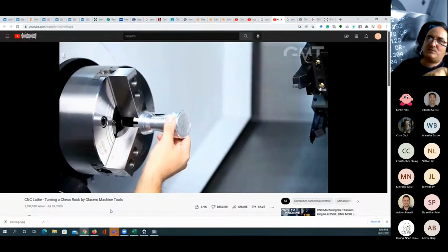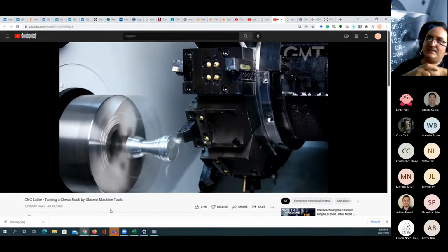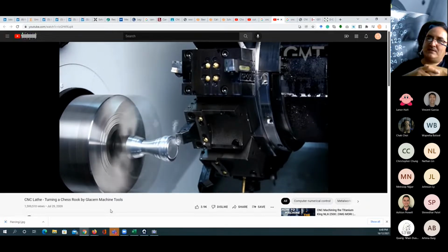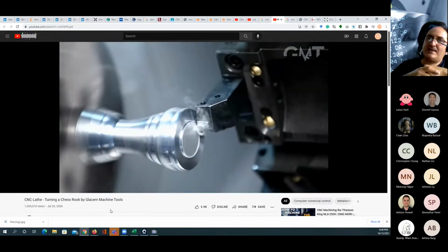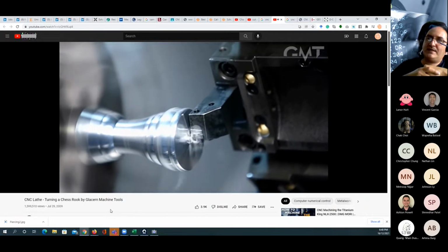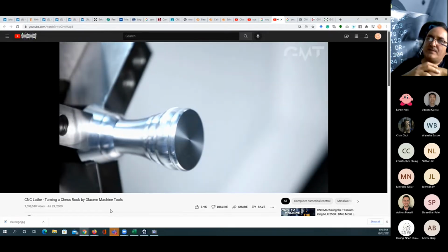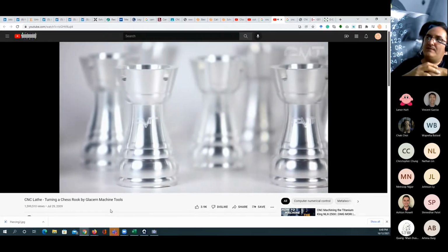Okay, now you can see this will be the shape we're going to achieve from the cutting by the saw. And what I'm going to do is just a single facing operation. It will go to the center, where it's going to be the X, the 0, but it goes a little bit further, and we're going to have the part.